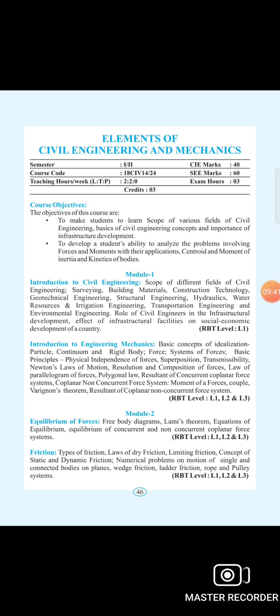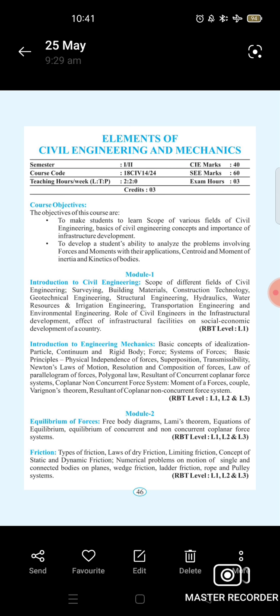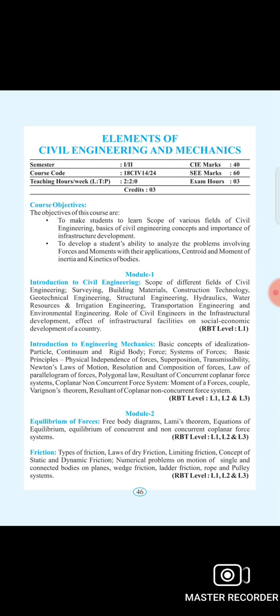Module 2 is about the equilibrium of forces: free body diagram, Lami's theorem, equations of equilibrium, and equilibrium of concurrent and non-concurrent coplanar force systems. In the previous module in engineering mechanics, we study the types of forces and where and how they act. Equilibrium is a stationary body subjected to external forces; if the body remains in a state of rest under the action of forces, it is said to be in equilibrium.